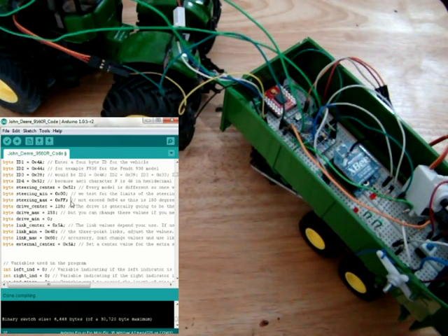Okay, now it's important when you're doing your testing that you remember that B4 is 180 degrees. So don't send the value above B4. But because we've set the limits from 0 to FF, whatever value we do send is exactly the value that we're going to send to the servo. So it's the exact angle. So that way we know exactly our limits.